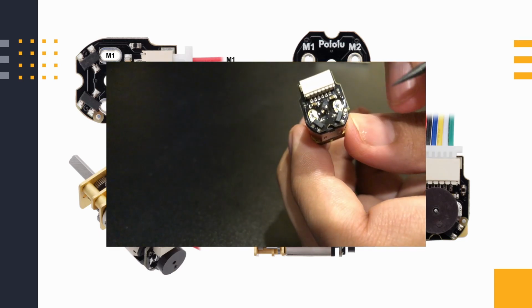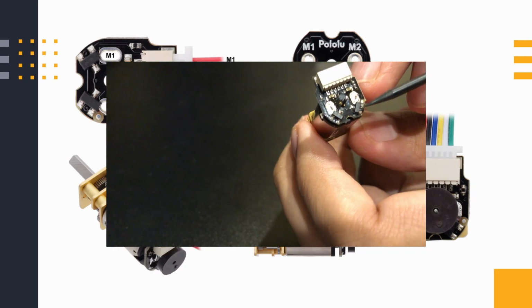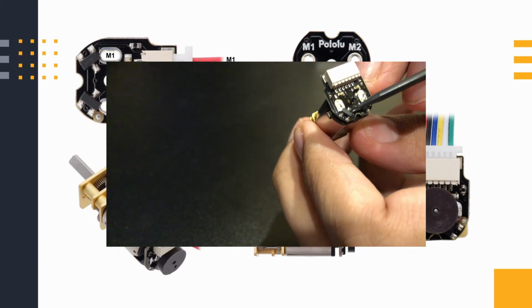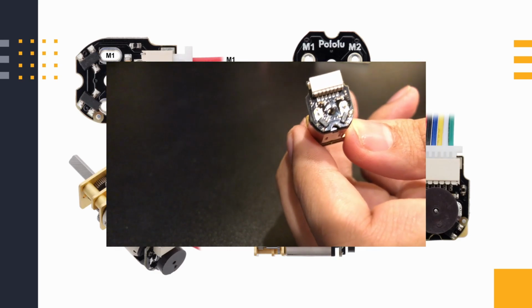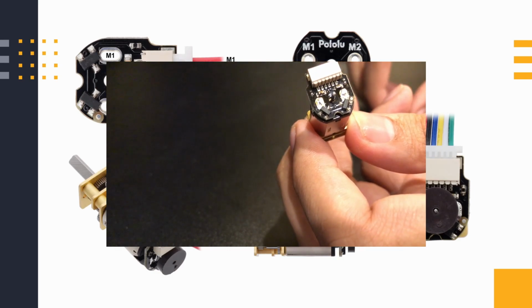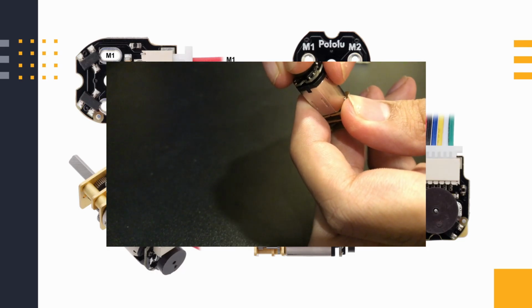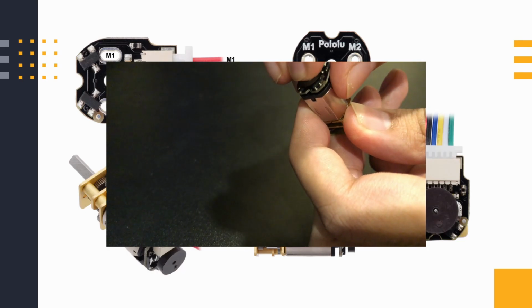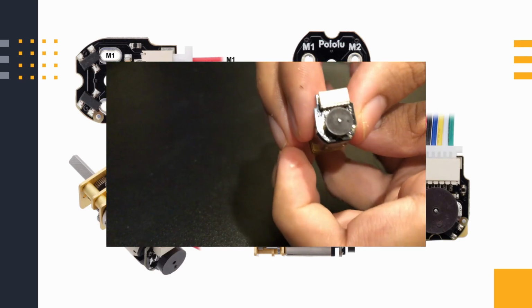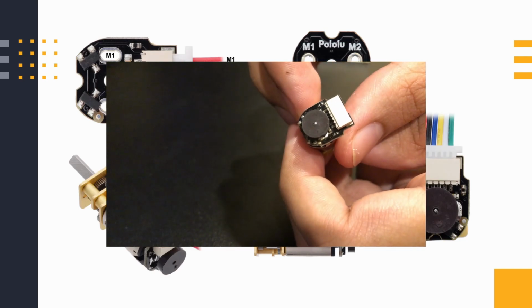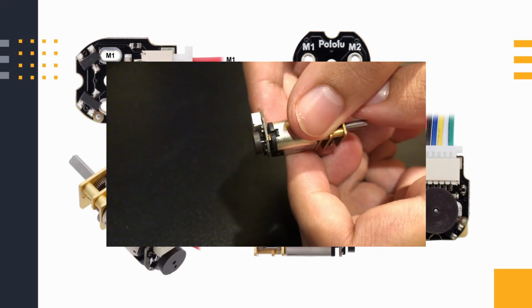What you do afterwards is you have to make sure these Hall effect sensors are facing out like this, so that when you put the magnet on, they'll be actually able to sense the magnet. I have accidentally done it backwards sometimes. Okay, there we go. Yeah, that's what it looks like.